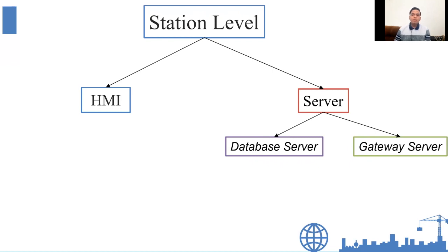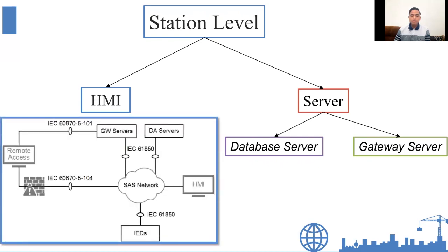The gateway server has a crucial role. It is vital that another redundant machine be provided as backup. However, both gateway servers always communicate with the field. The master station performs the redundancy by choosing which gateway server to communicate with. In other words, both gateway servers are configured as master, hot or hot. A typical arrangement of gateway server and database server in SAS is shown in figure 2.